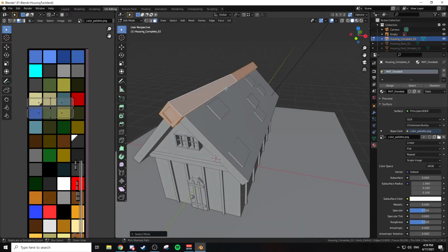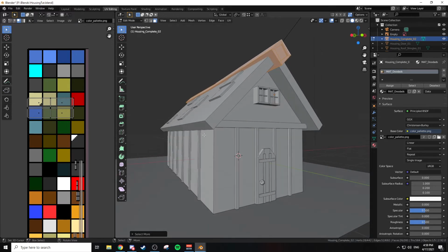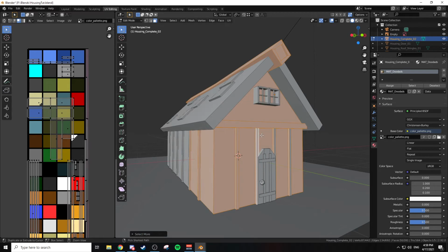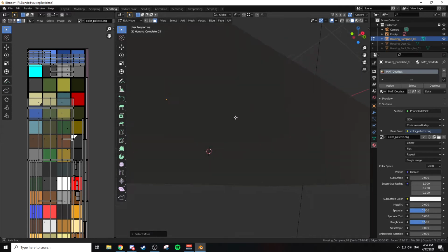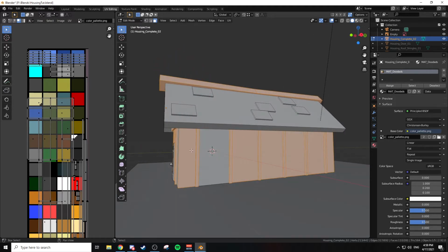So we'll just do Control++ on all of that. Let's grab these wood panels. Now if we do Control++, is it going to grab the walls? It is. Okay, so I'm going to hold Control+ down so it selects everything there. And then I'm going to hold down Shift and right click these walls that I don't want.